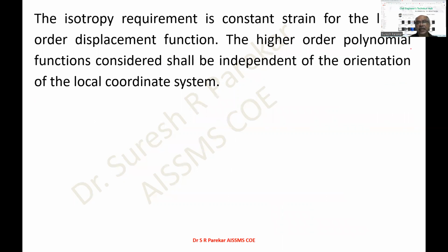The isotropy requirement, now you can see this requirement is constant strain for the linear order displacement function. Means constant strain and your displacement function is linear. Strain constant, displacement function is linear. The higher order polynomial functions considered shall be independent of the orientation of the local coordinate system. So this is again most important one. It is again independent of the local coordinate system.